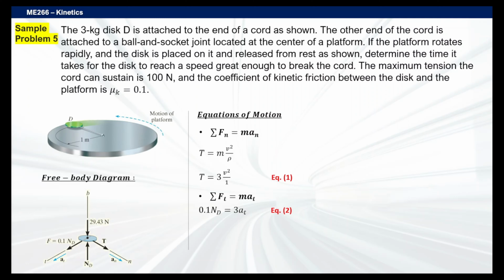That'll be our equation 2. And then, of course, finally, we have the binormal direction, or I just call it the z-axis in a general sense, which is technically a summation of forces equals zero because there's no acceleration on this particular axis. It's just moving on this tangential and normal acceleration plane. There's no moving up and down here. But for F sub B, we have the weight and the perpendicular force opposing each other, so it's going to be represented as such, okay?